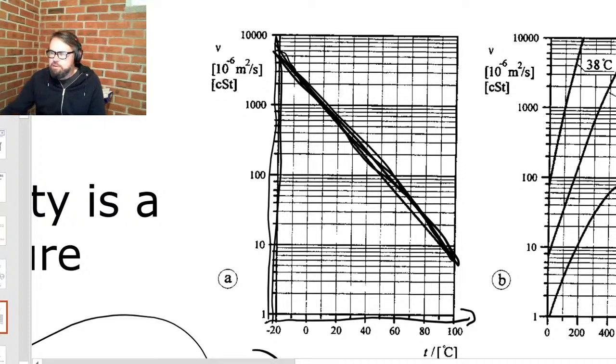That means that you need to be at a certain particular point in this scale, because if you started here, then this kinematic viscosity is very high, and it may restrict the flow rate in the system, and it may not be able to produce enough pressure in certain locations.